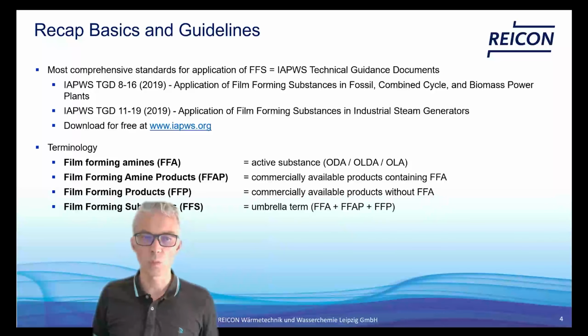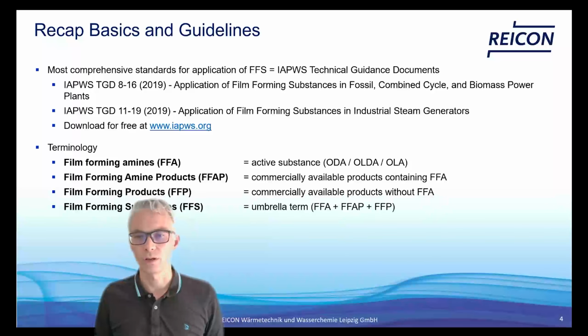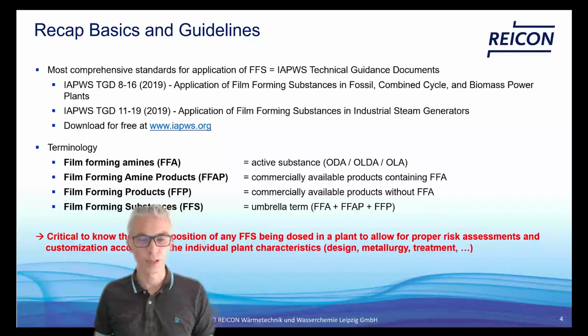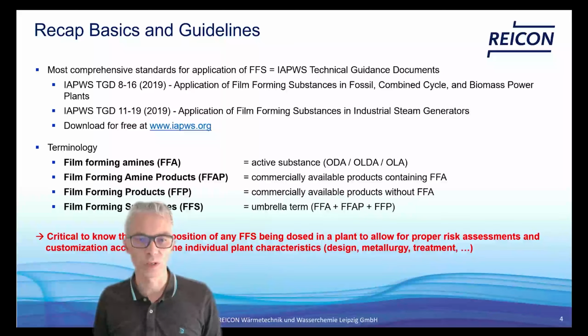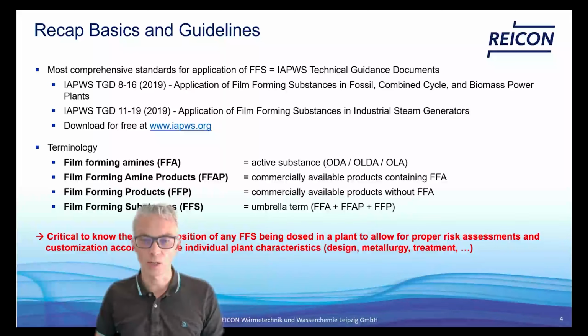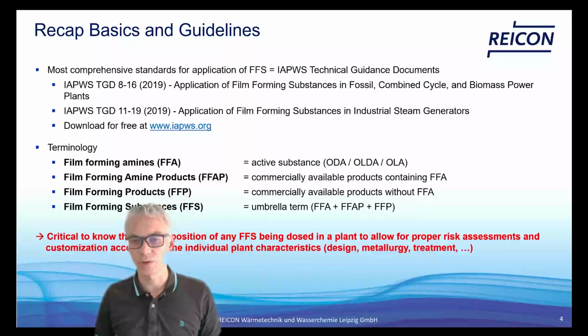And there are the film-forming products, which contain no FFAs, and film-forming substances is the generic term for all three different types of products and substances. It's always critical to know the full composition of the film-forming substance you are planning to use, because for a proper risk assessment and also for individual design of the process, you need to know exactly what you're using to specify the application.